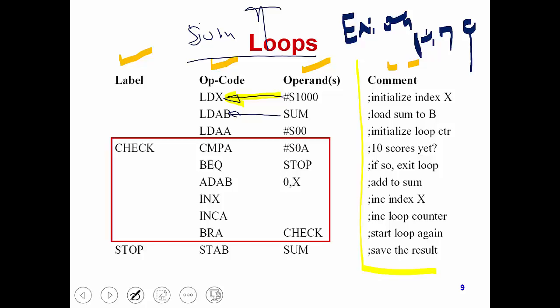If you turn to page 61, you see some examples of data directives. FCB is to form a constant byte, and we reserve memory. We also load the value inside. Then we label it. So this label, for example ABC on page 61, is pretty much similar to the SUM here.